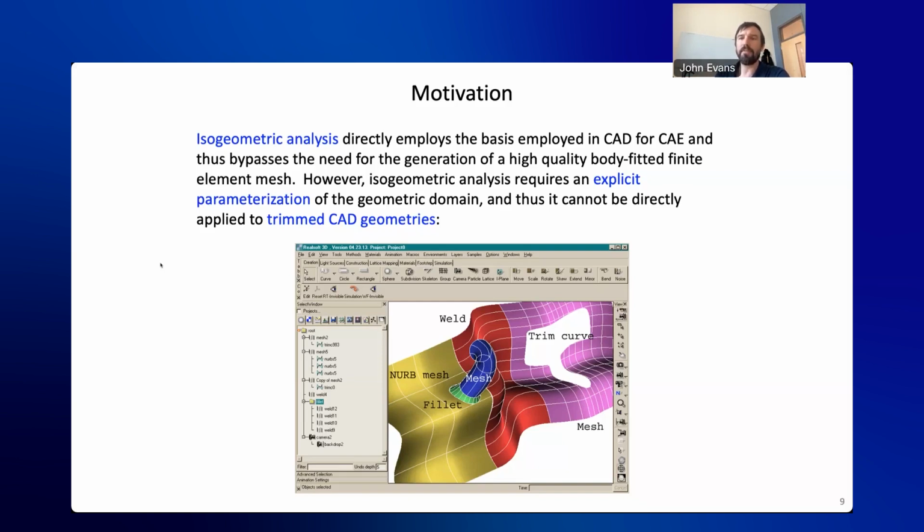And the problem is even worse in 3D. And this is due to the fact that in CAD, especially described using B-reps or boundary representations, we describe volumes by their bounding surfaces, not by parameterizing the volumes instead. So my old student Luke Engvall used to joke that SolidWorks really should be called Surface Works as a result.